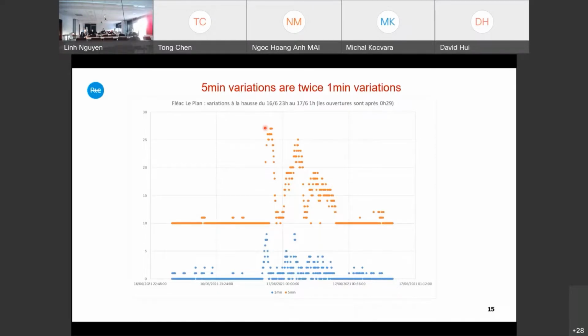And this leads us on this line to have a 10% margin. As we can act in 1 minute, we need a 10% margin. So we need to operate the line at 90%. And if the line comes to 91%, as it will take roughly 1 minute to switch off some wind farms, we have to start switching off right now to cover the risk of what increase could happen in 1 minute.